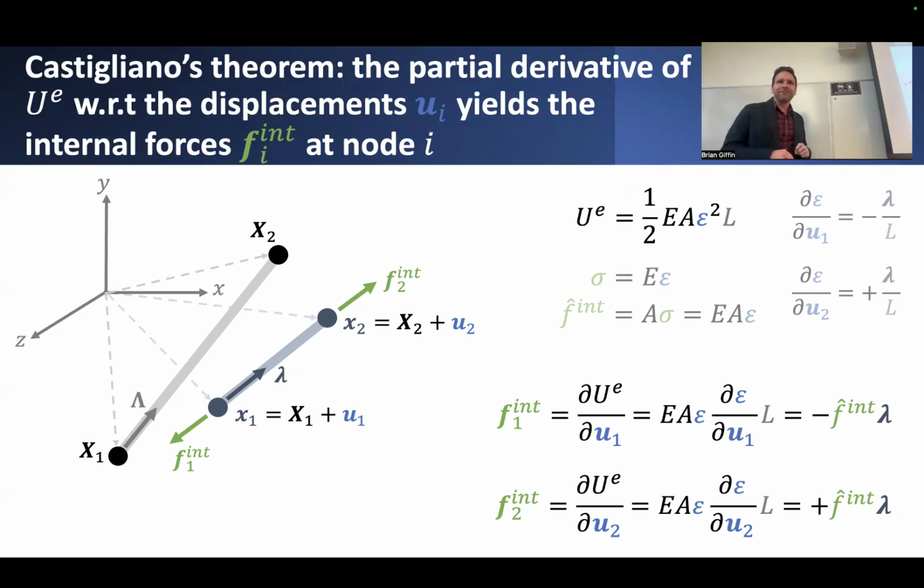In the case of small deformations, if we use that linearized strain assumption, we would basically have to replace lowercase lambda with this original lambda, saying that, well, we would assume that if the axis of this member isn't changing very much, then these forces will actually act along an axis that is parallel to the original undeformed element's orientation. But that stops making sense as soon as this element maybe rotates significantly.